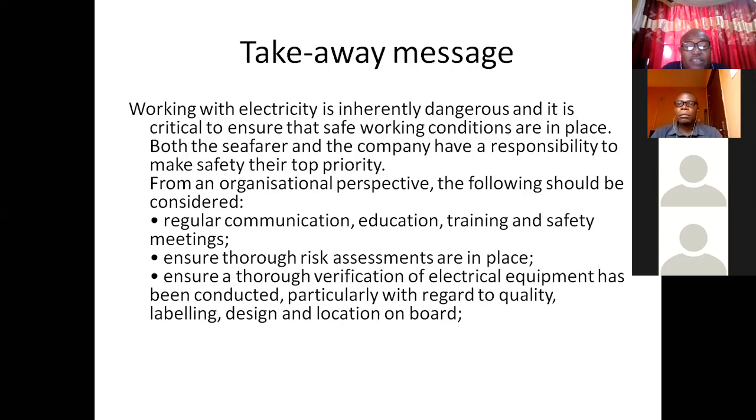And that makes us exposed to what? To hazard. Ensure risk assessments are in place. You assess risk before you carry out the job. Every job has a risk, so the best option is to assess the risk before you even do the job. Ensure that a thorough verification of electrical equipment has been conducted with regard to quality, labeling, design, and location before you carry out the job.